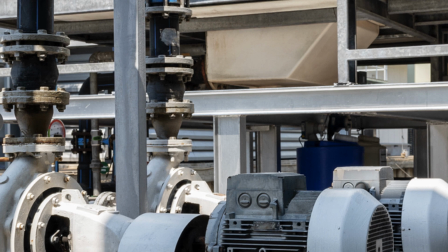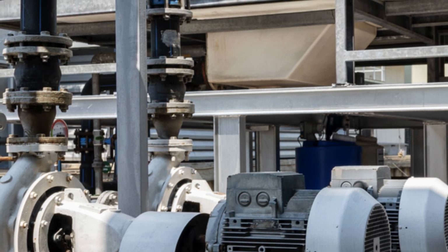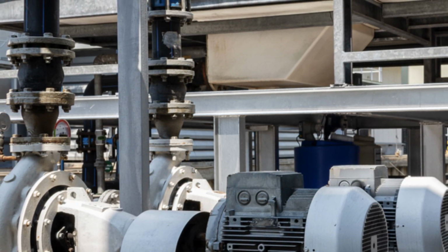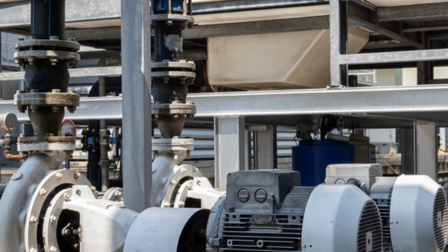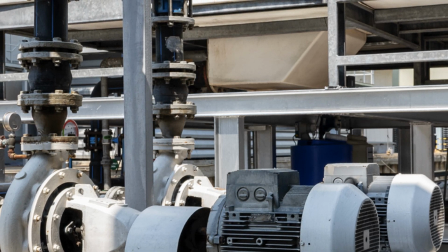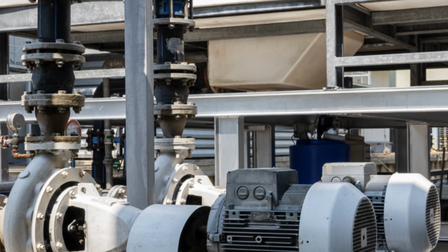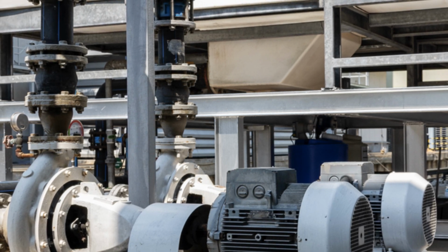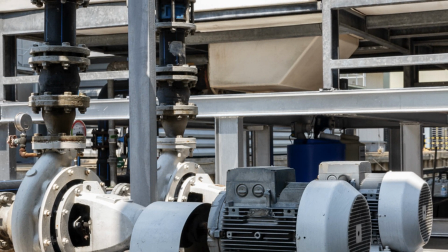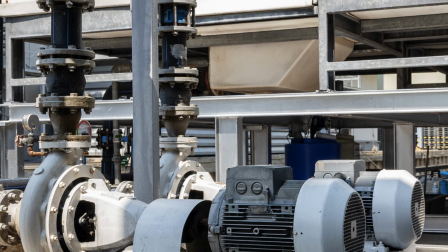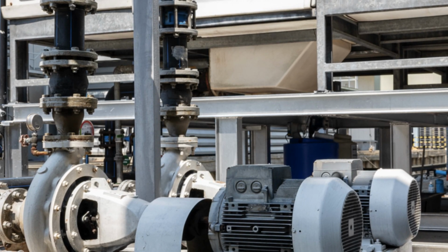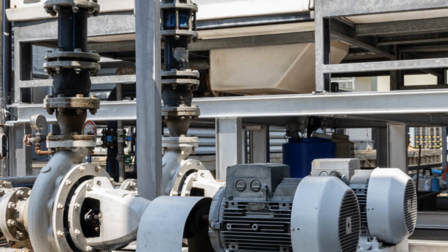Gradual heat buildup in rotating equipment. A steady increase in temperature over time in motors, gearboxes, or rotating machinery often indicates worn bearings, unbalanced components, or insufficient cooling. This progressive overheating can lead to increased friction, thermal expansion, and eventual component failure. Regular thermal monitoring allows for early detection, enabling proactive maintenance to prevent costly downtime and extend equipment lifespan.